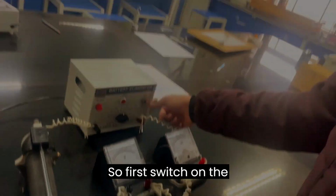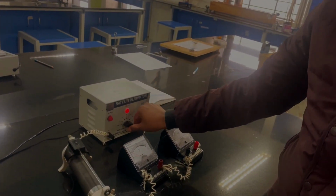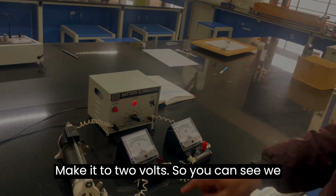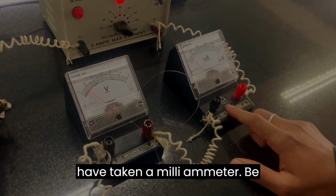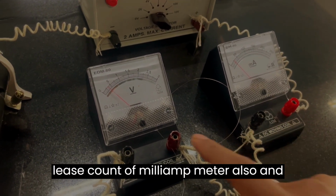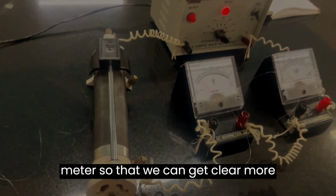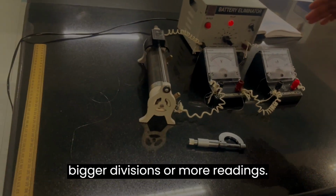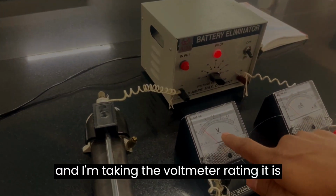So first switch on the eliminator, make it to 2 volts. So you can see we have taken a milliammeter. Be careful about it. You have to measure the least count of milliamp meter also and voltmeter also. We have taken milliamp meter so that we can get clear more bigger divisions or more readings. So first I've kept the battery to 2 volt, and I'm taking the voltmeter reading.